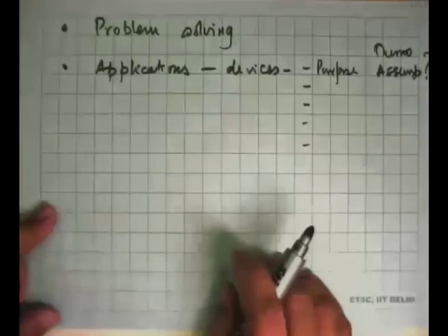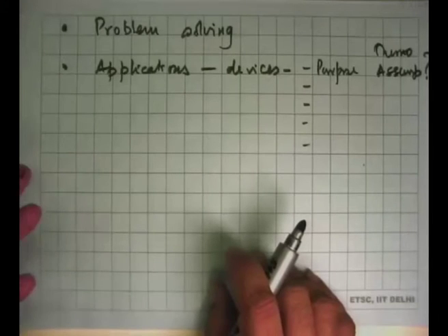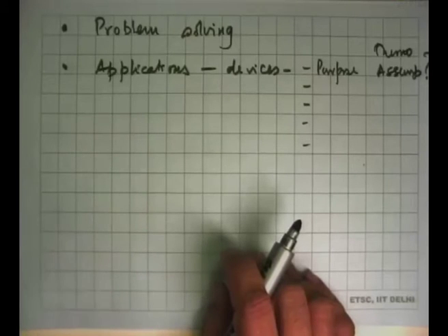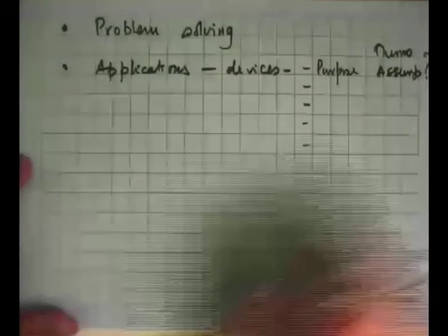The simplest way to look at a boiler or any heat transfer process or a condensation process is constant pressure. What about a turbine or a pump or a blower or a fan? We consider the ideal case to be isentropic. A pipe connecting these devices, we said it's an ideal flow, with no pressure drop in the pipe. In this beginning course, those assumptions are fine.